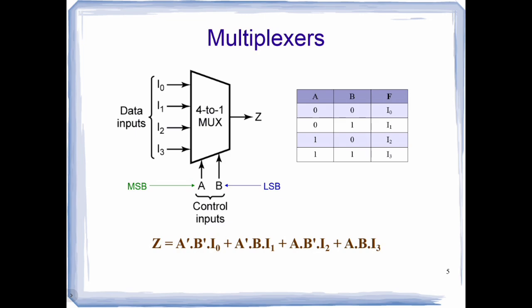Now we talk about 4:1 multiplexer. The figure shows a 4:1 line multiplexer. Each of the 4 lines I0 to I3 is applied to one input of an AND gate. Selection lines are decoded to select particular AND gates.